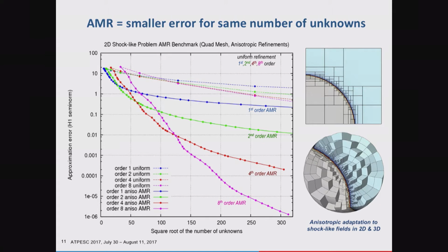When you do adaptation with these types of meshes, you notice that the degree of anisotropy you can get, for example, where it's at 45 degrees, you can't get any anisotropy. And in a problem like this, you would really like exceedingly high anisotropy. So one of the advantages of more geometrically based conforming adaptation is you can get that higher anisotropy.